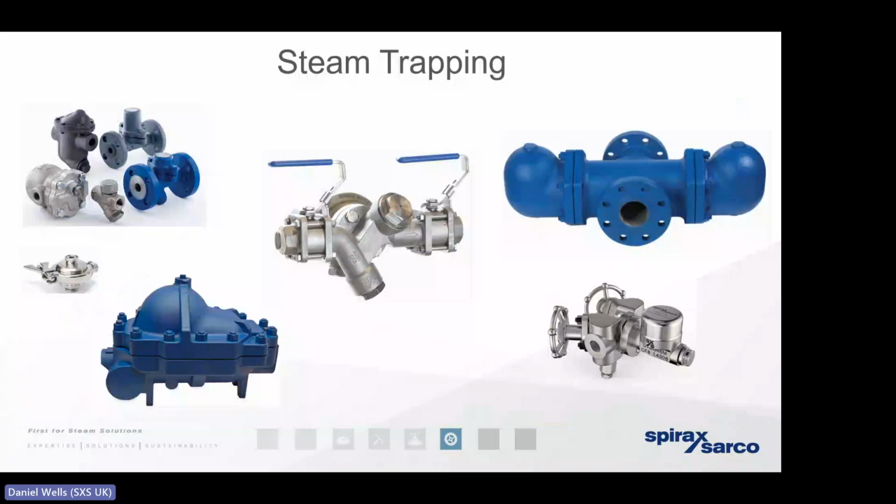So moving forwards, the topic of steam trapping, as I've mentioned, I believe to be critically important, perhaps more important than the heat exchanger itself. Because if our steam trap is undersized, poorly selected, poorly maintained, poorly installed, it's highly likely to fail. It will have a high cost of ownership, and it's highly likely that if and when that steam trap fails, it will result in those costly and unnecessary emissions.